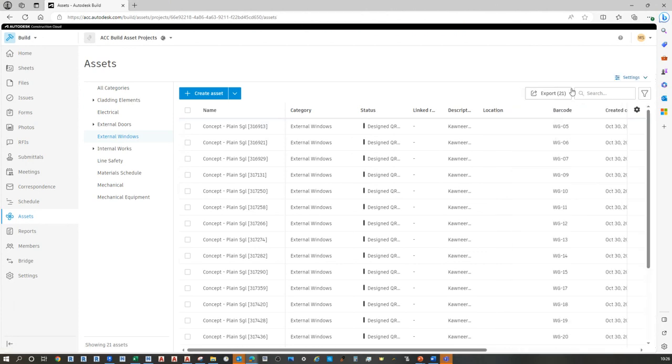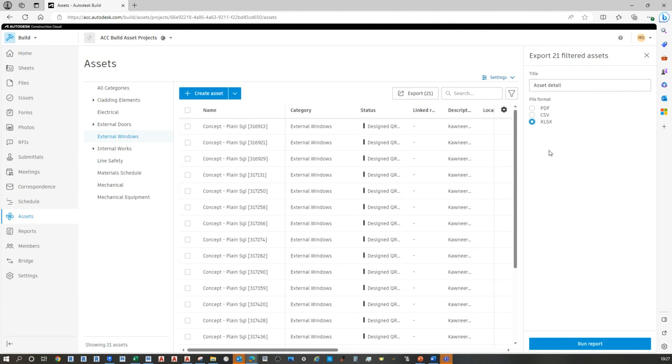And so now, to create almost a circular reference, we could export all of this out to an Excel to essentially create an asset register outside of the ACC environment. Whereupon then potentially we could use it with the import assets if we wanted to potentially update any information that may not be in the Revit model that we could have created from, let's say, a product data template that somebody could create within the ACC environment.